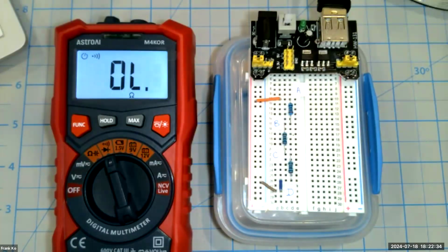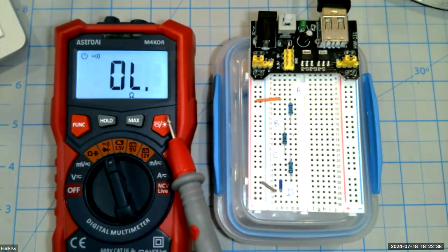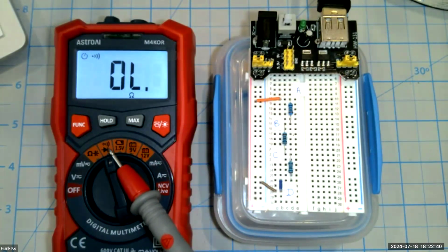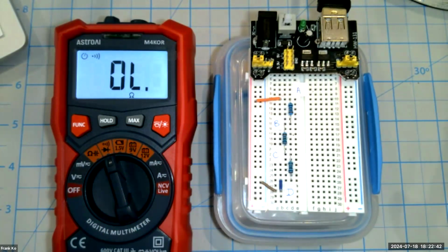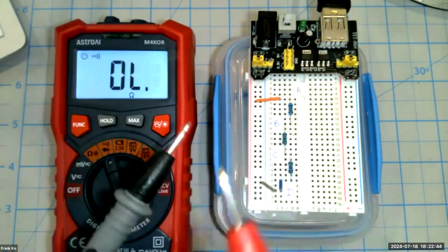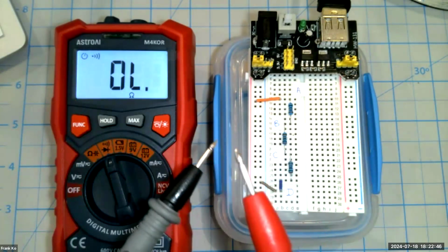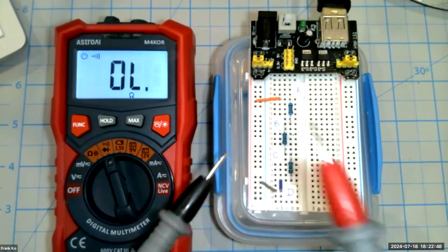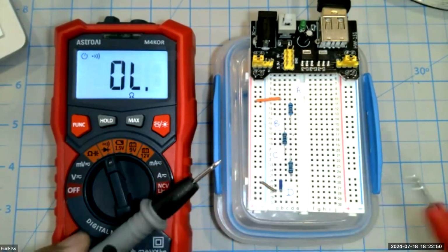Okay, we're now in camera mode and I've got my multimeter set up, turned on, backlit, and it's got to be on continuity because again, every time before we do any measurements with the probes, you want to make sure that the probes are properly connected and they are working properly. So we're going to do what's called the continuity test.